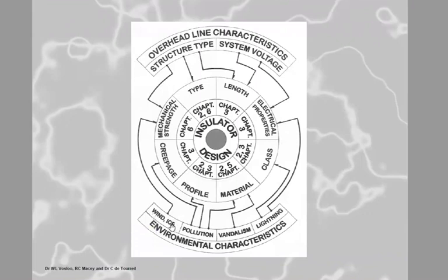And then obviously, believe it or not, in Africa, we've got ice and snow loading. And so that all will influence your mechanical strength. The wind will influence your mechanical strength, and the ice loading. I mean, in Sweden, you can get up to 1 meter diameter ice on a conductor. Can you imagine the weight? Okay. I don't know if you guys have got that.